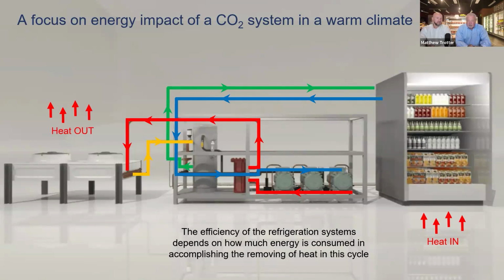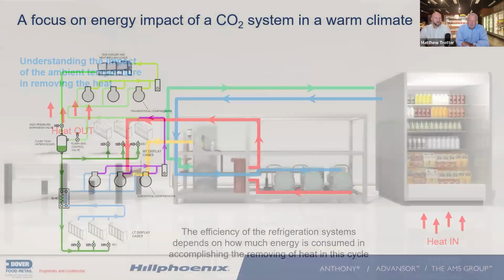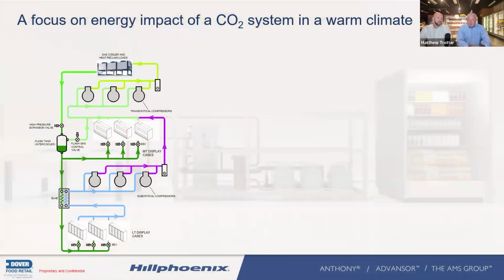Okay, what impacts CO2 is the ambient. And what is that temperature differential? What is it that we need to do to get the heat out of the system? And the more heat we get out of the system, the more the system runs. So again, refrigeration cycle doesn't change. We just have a little bit more of an impact with the ambient condition. So when we understand that, we have to look at how that operates.